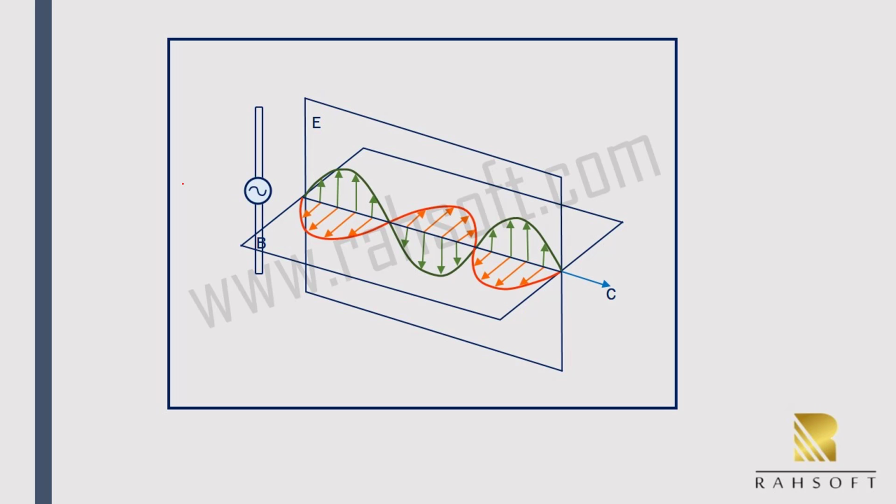So this is a part of the electromagnetic waves sent out from the antenna at one instant of time, and the electric and magnetic fields are in phase and perpendicular to one another and to the direction of propagation. Clearly the waves are shown only along one direction, but they propagate in other directions too. Electromagnetic waves generally propagate out from the source in all directions, sometimes forming a complex radiation pattern. A linear antenna like this one will not radiate parallel to its length. For example, the wave is shown in one direction from the antenna in the figure.